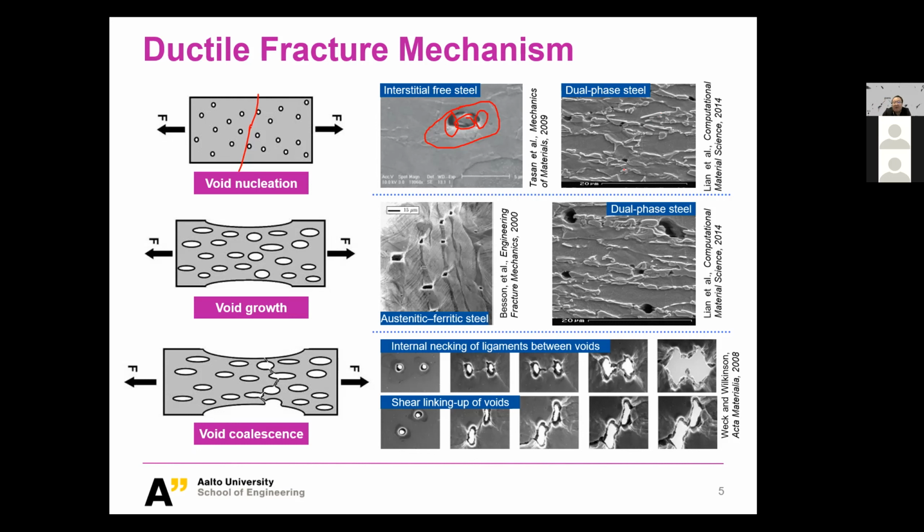And this is typically how you do it in, let's say, metallic materials. As you can see, we would have a hard phase and a soft phase. When you just deform them, everything's deformed horizontally. And you would develop these kinds of voids as well, because the mechanism is the same. The soft one is already deforming, but the hard one is not. So they will just detach from each other, and then you will develop some kind of voids.